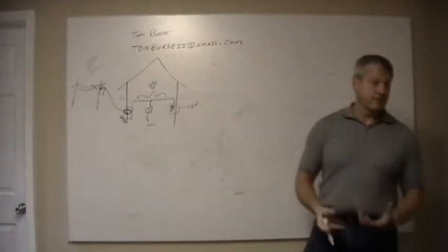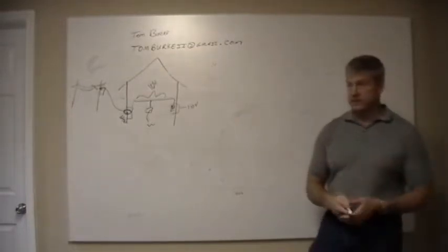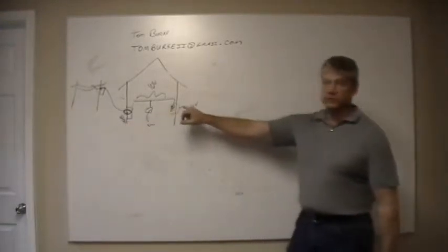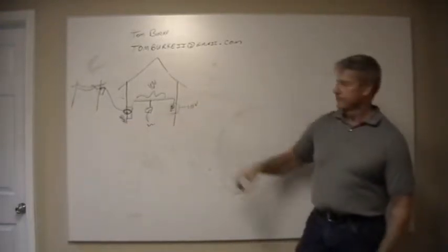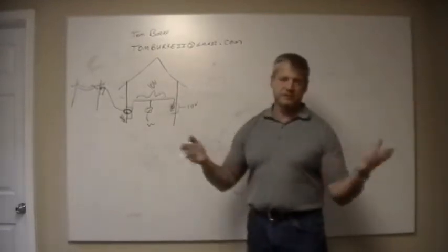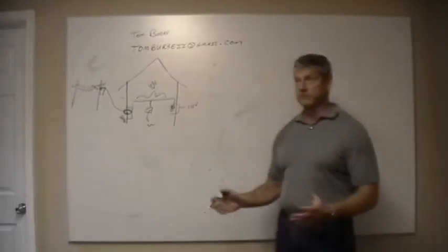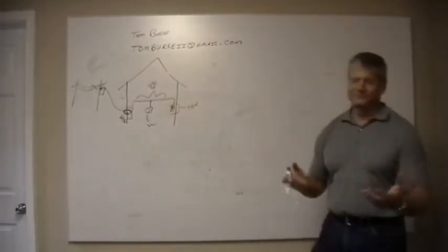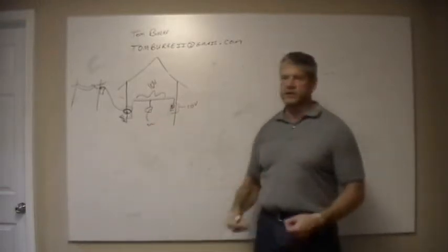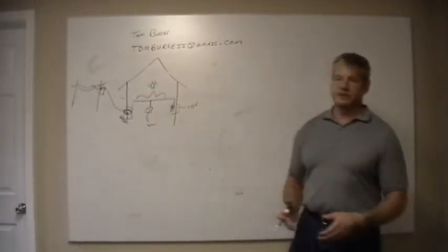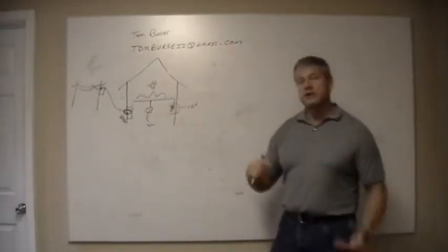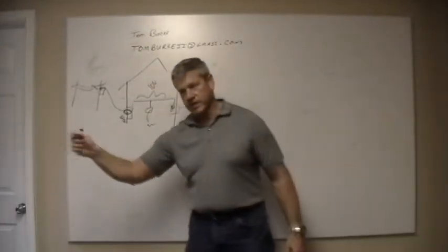So what that practically means is if you're designing a circuit that has to plug into the wall, it has to be able to accept anywhere between 120 and 110. And then you hear people say, oh, but usually it's around 115. It's in the middle, people call it 110 volt, 115 volts. So here's somebody talking about 110, 115, 120 for household voltage. They're talking about the same thing. It could be anywhere from 120 to 110, depending on the load and how close you are to the breaker box.